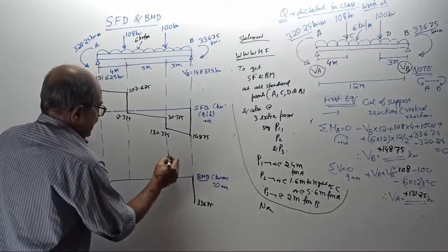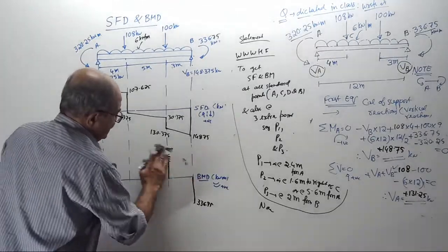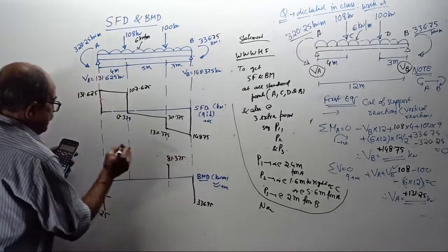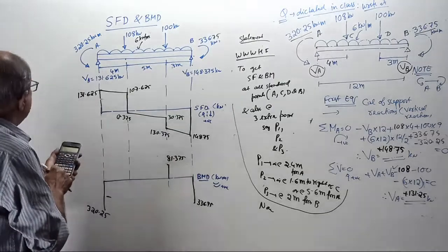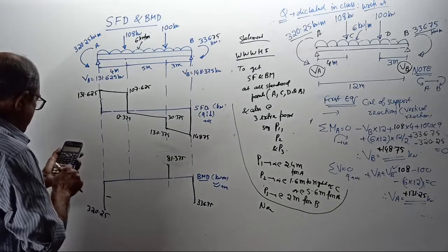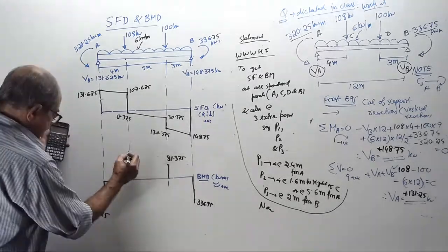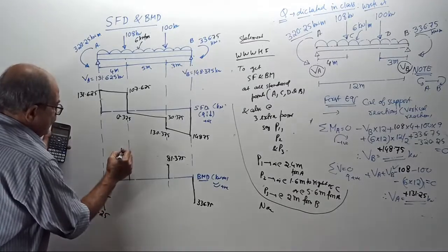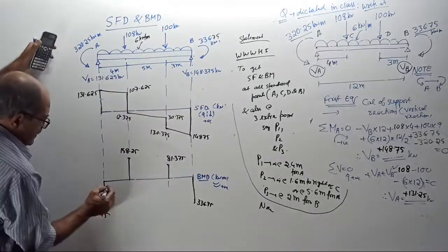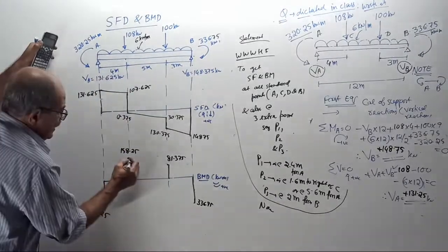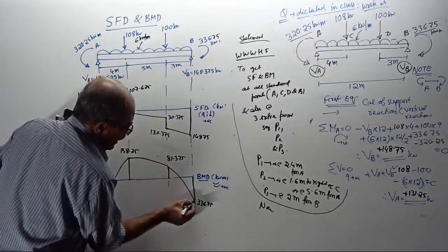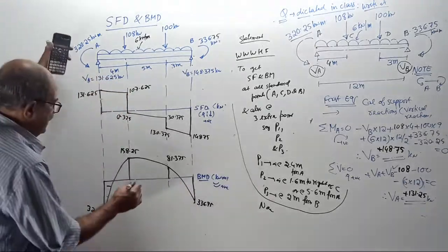It is plus 81 point something here, a little lesser. This is plus 81.375 here. Bending moment here is minus 320.25 plus 131.625 into 4 minus 6 into 4 into 2, which is 158 point something here. Out of scale, 158.25. Okay. Now, joining will be a parabola this way, then it will become this way, a parabola once again, scale no problem, and one more parabola here. I have not bothered too much about the variation, plus minus.